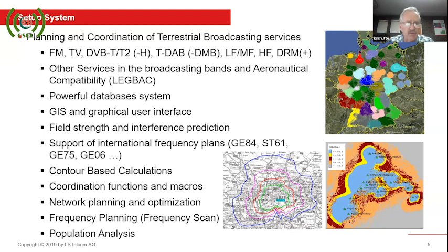Then specifically for DVB-T2, we definitely need to look at the GE06 plan and all the DTT information that is in that for your country and all other countries that fall within the coordination distance vector for your country.